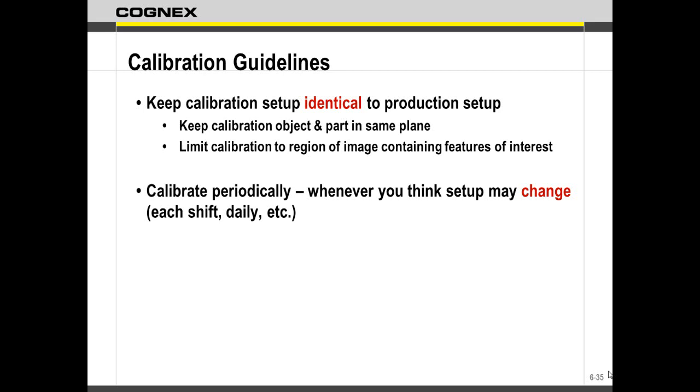Depends on your accuracy. Now, when you're trying to decide on a camera, I always caution people to stay away from hard limits. So like in our program, we have an edge tool. We have a fine patterns tool. So we're talking about less than half a pixel of accuracy that we're having to add here. Now, when you're dividing out what your tolerance is, you should make sure your tolerance, if you're plus or minus 3 microns or something, let's say, make sure those 3 microns equal to about 5 pixels. I say 5 pixels because that gives you some wiggle room. That means you are well away from your tolerance there. So the information you're getting back, you can trust.